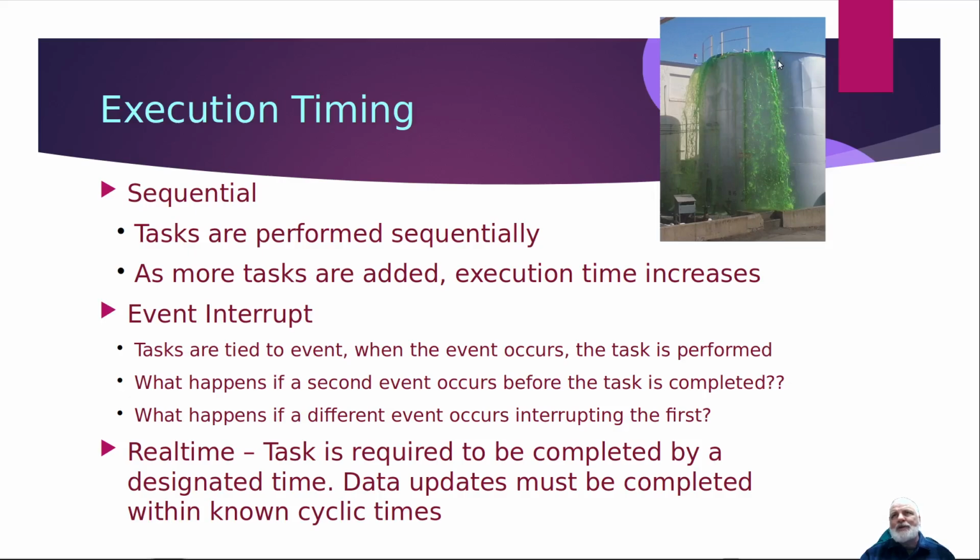So that gives you a little bit of time between the sensor sending the message to the controller to shut it off and the tank actually overflowing, right? So you build into it a little bit of delay time that's okay. But then you run this controller that you know is going to get back up to the top of that event if it's sequential, or have time to take care of any other interrupts and get back and finish shutting that pump off before the tank actually overflows.